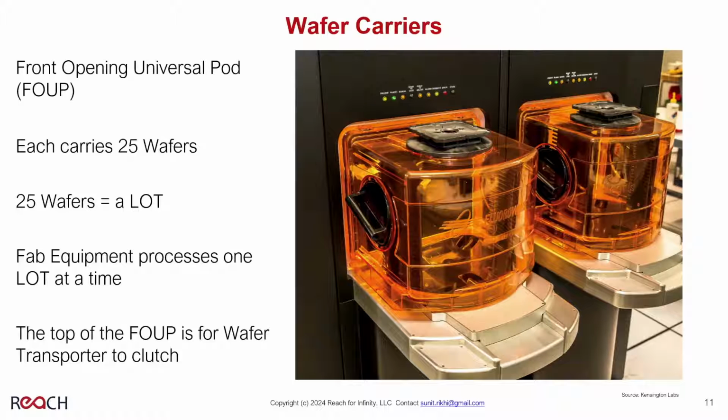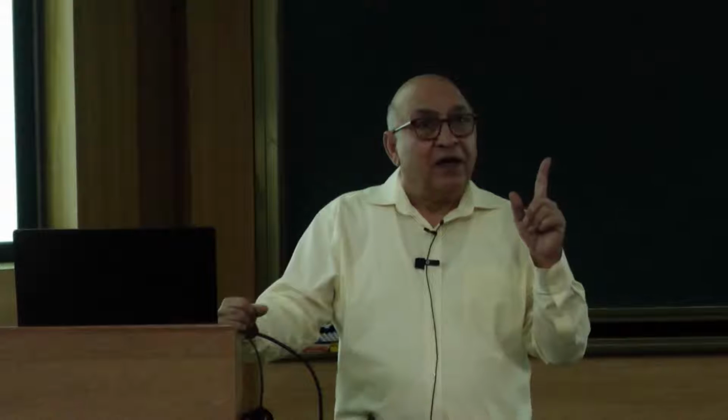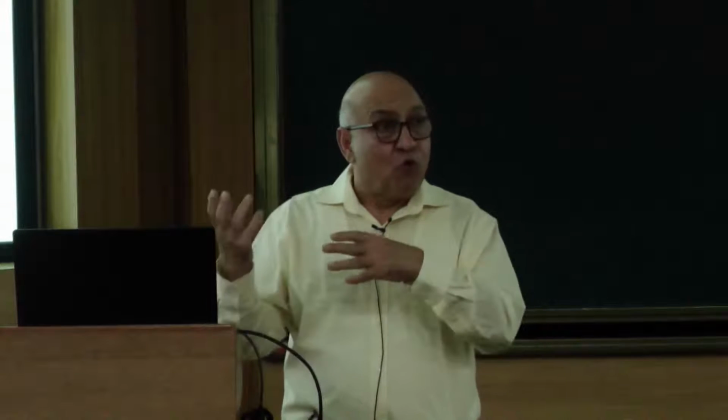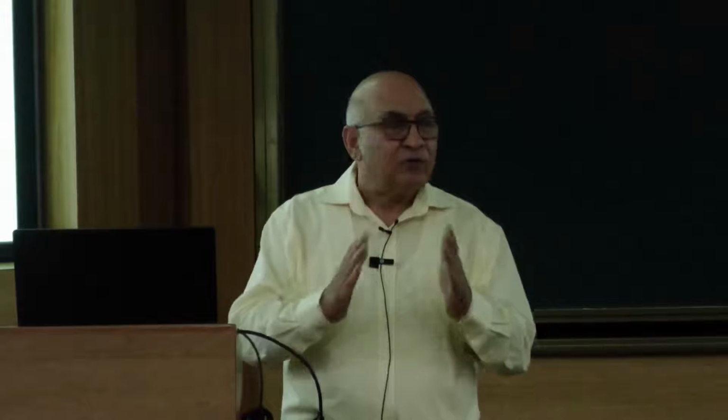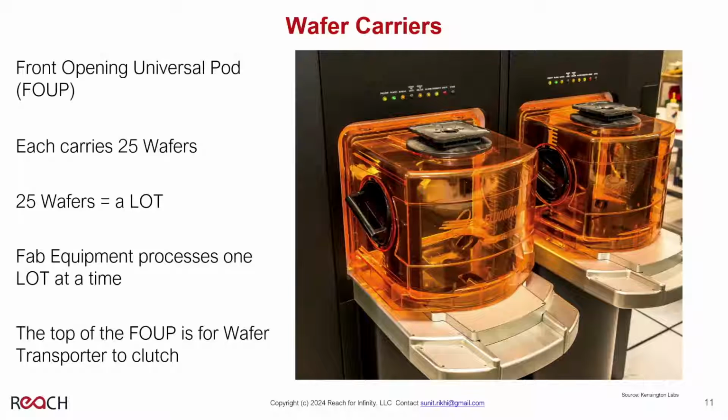Each FOUP has 25 wafers. We chose 25 because intelligent people ran lots of software to optimize how much should be processed by a tool at one time. If it's less, it's not optimized. If it's more, it's not optimized. So 25 was selected, and each fab equipment processes one lot at a time.